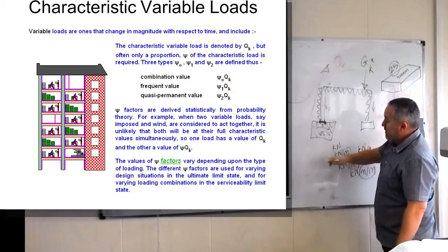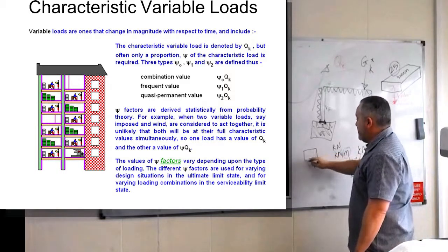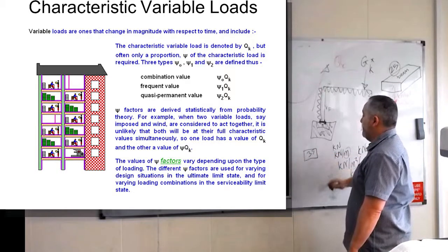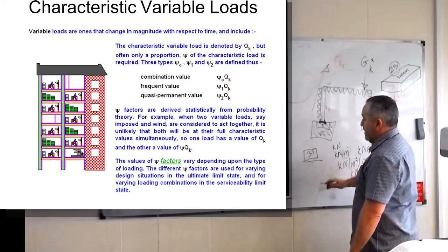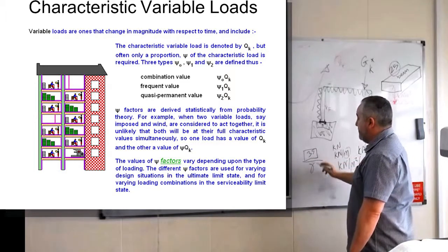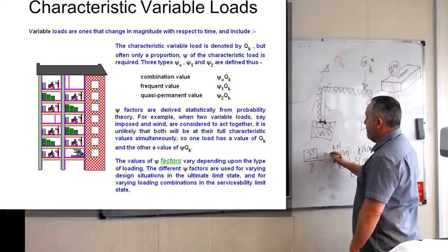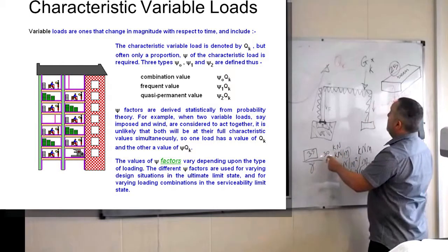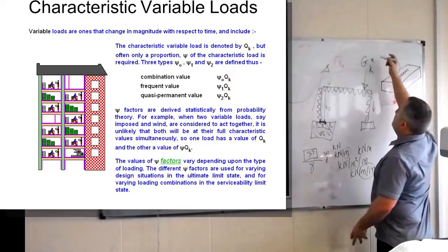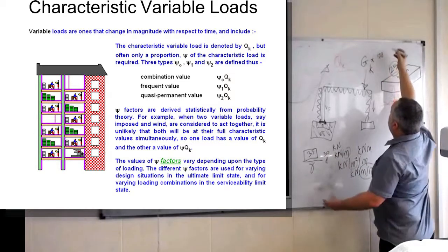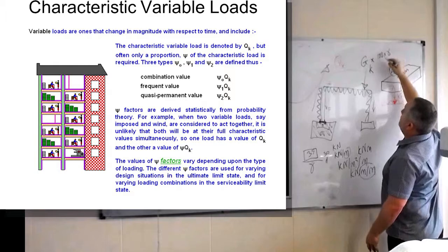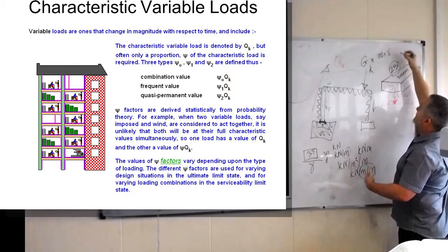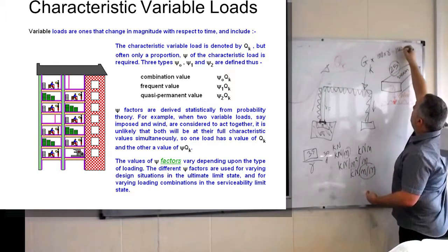When we've got a material, and say we thought it was 35, we divide it by something so that it comes to something like 30, and that's what we design with. So we reduce the value. When it comes to loading, say that was 100, we will apply a factor of safety so that we increase it, and say that it was 150.